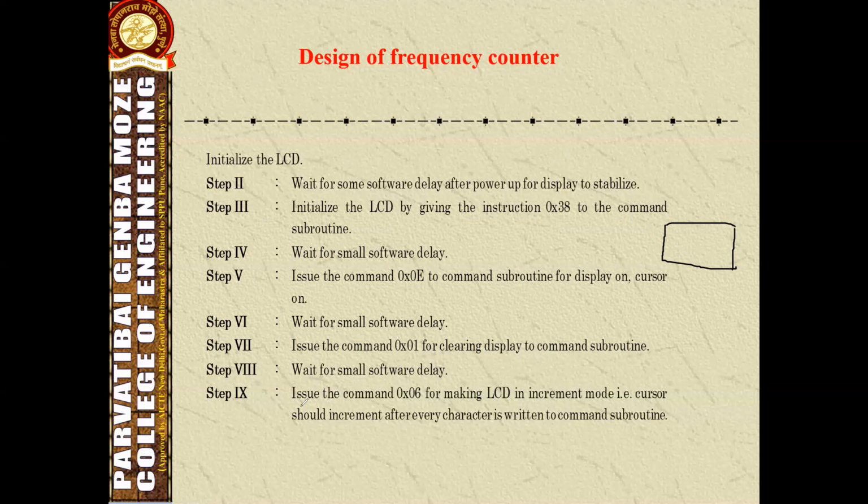And after that, similarly issue the command 06 to the command subroutine for making the LCD in increment mode, so that the cursor increments after every character is written.